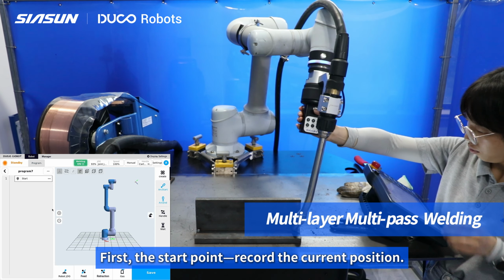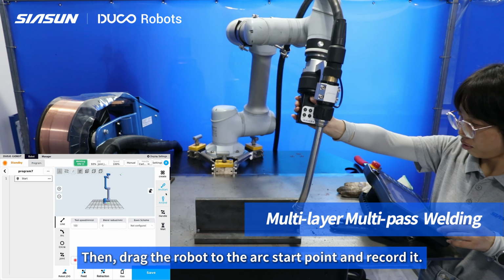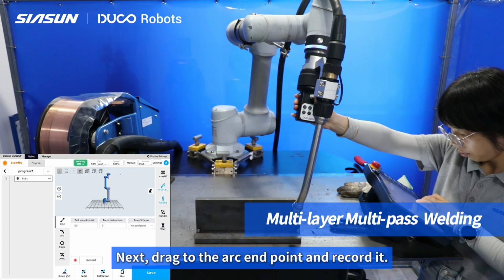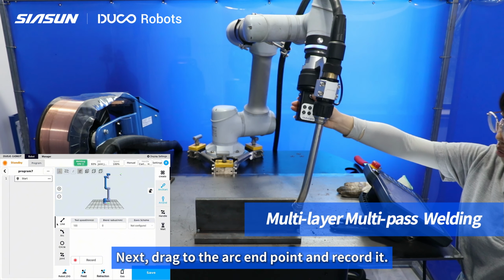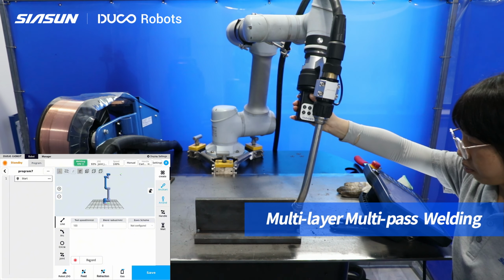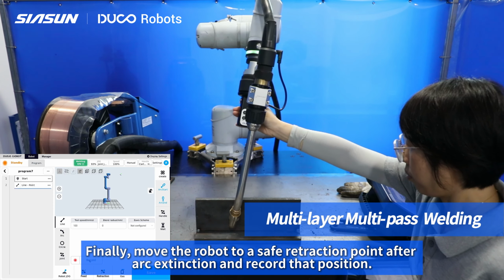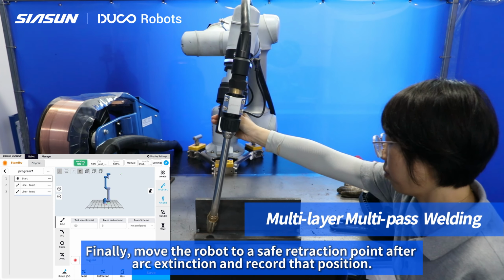First, the start point, record the current position. Then, drag the robot to the arc start point and record it. Next, drag to the arc end point and record it. Finally, move the robot to a safe retraction point after arc extinction and record that position.